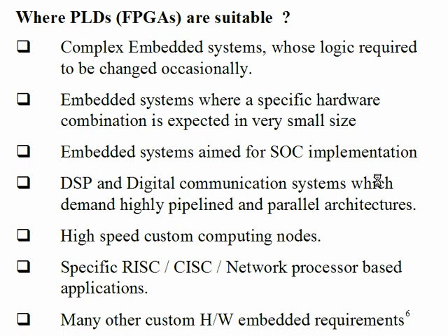Because rather than configuring the multiplexers and lookup tables to do your job, you directly write the code for it, directly implement it at the silicon level. You get more speed. But the point is, a lot of cost is involved. And as you know, when the complexity of the embedded system is going high, the likelihood of using more numbers of products also goes down, correct or not?